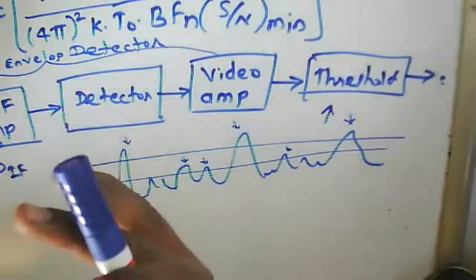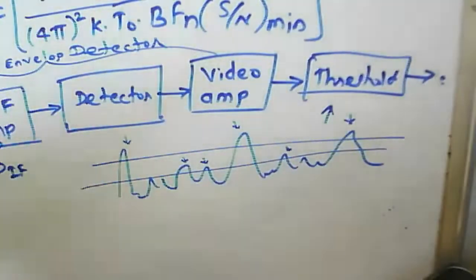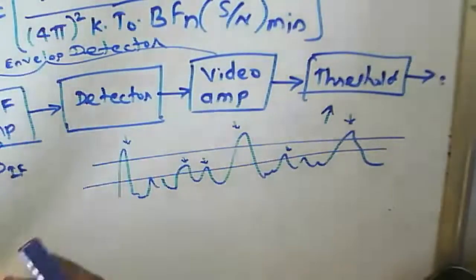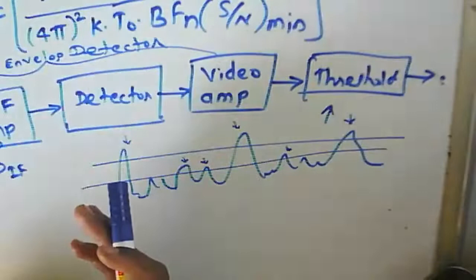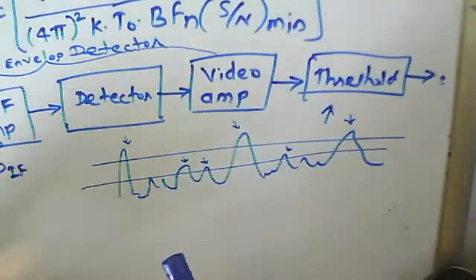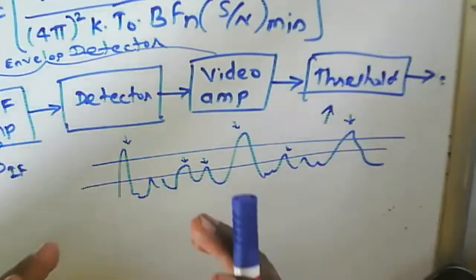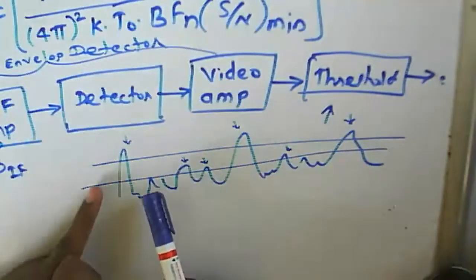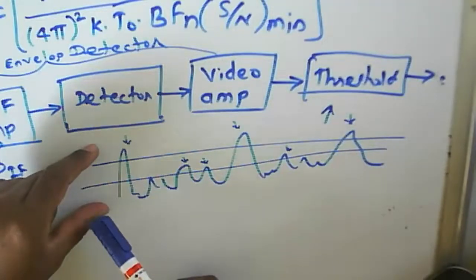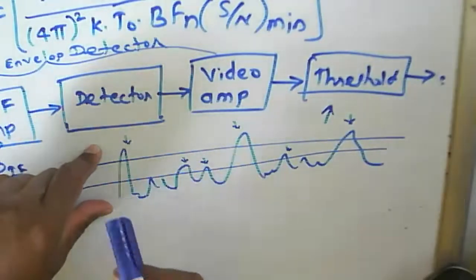Forget about that; we are getting the echo signal, then the receiver is detecting the echo signal. And out of those 100 detected signals, how many will be detected falsely? That is to be found out as the probability of a false alarm.